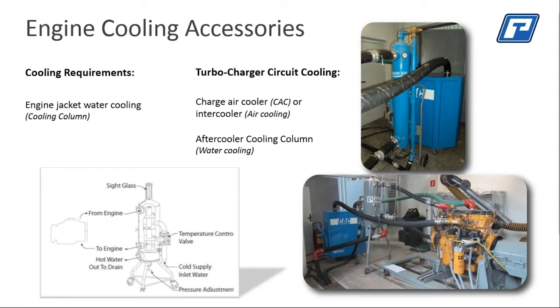The difference is there's an integrated heat exchanger built into the engine, and that heat exchanger is cooled by water. So we are taking water from our water circuit, and we are flowing it into the engine-mounted heat exchanger and removing the heat from the air prior to entry into the intake manifold on the engine. I hope that breaks things up for people relatively well.